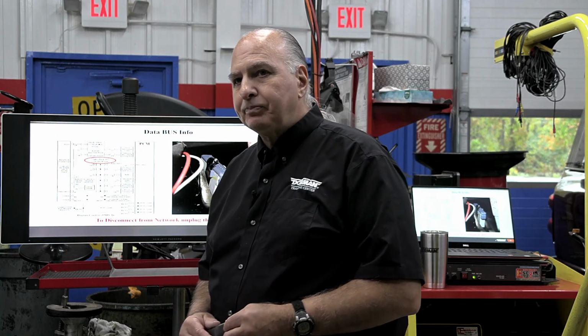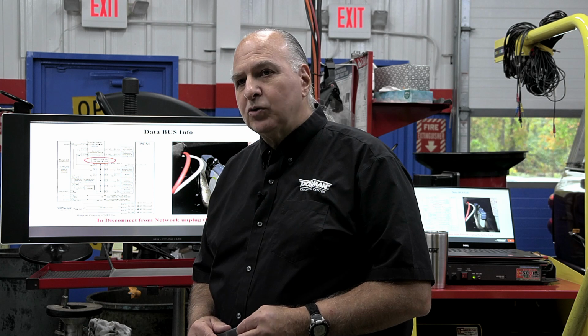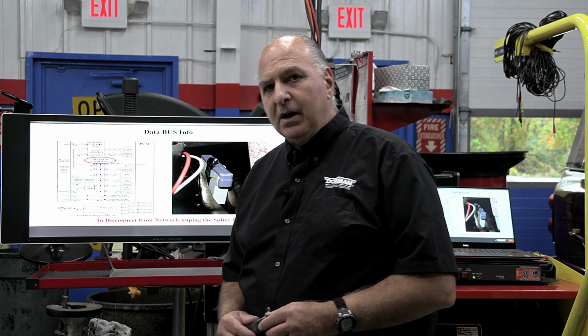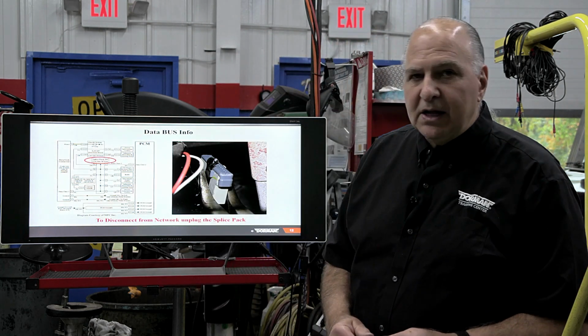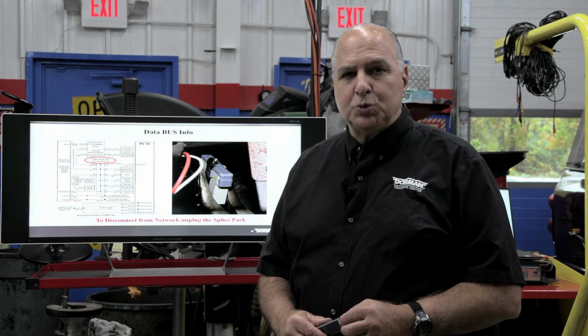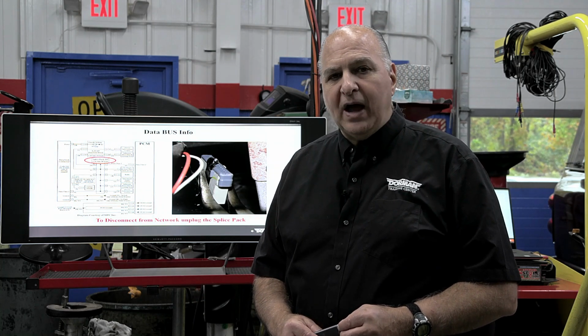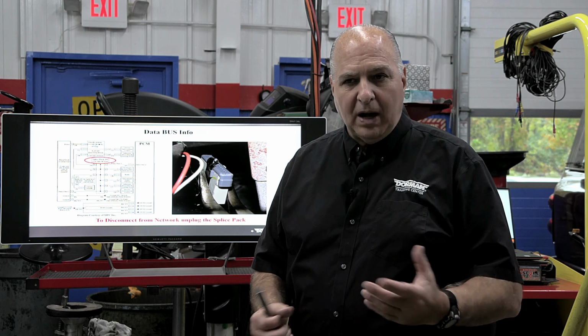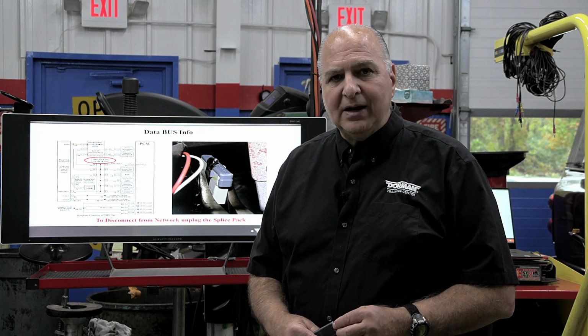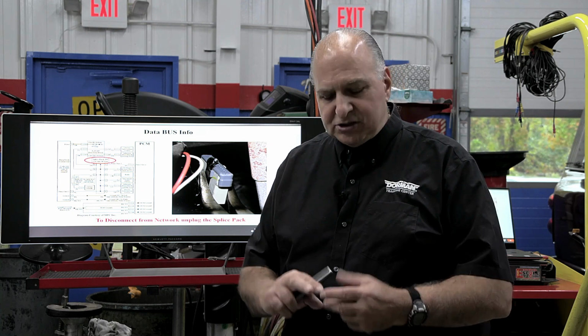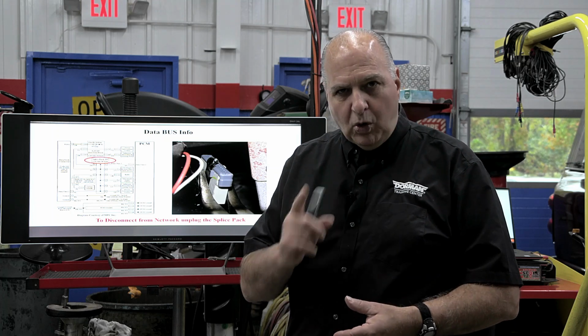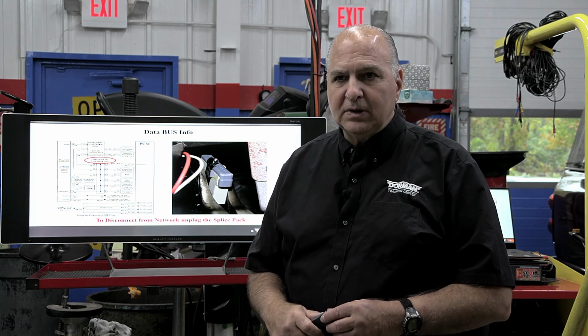computers. Okay, we got a couple of questions. Can you extend a twisted pair? Could you extend the twisted pair? Yes, you can. An easy way to do that is take the same gauge wiring, make sure that you connect them together by solder heat shrink, and take a drill and basically make sure you got at least 1 twist per inch. Any other questions?